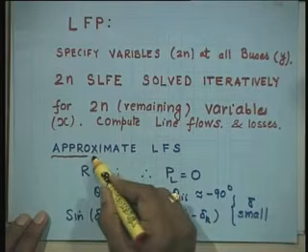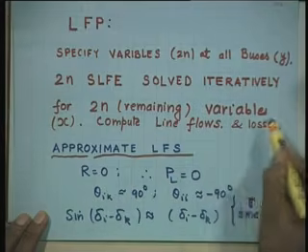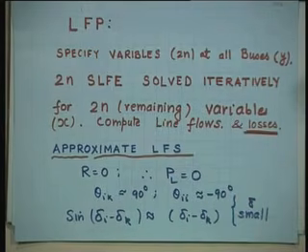Sometimes we need to conduct an approximate load flow. How do you get transmission line losses computed? Add all the line flows. Having computed line flows, just add them, one more computer command, add all line flows. If it is 0, it is the ideal situation. If it is not 0, which is the practical situation, it gives you losses.